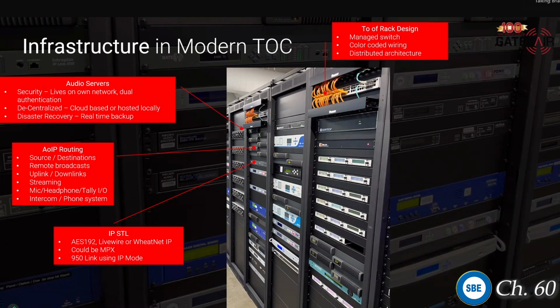And the beauty of that is that with the IP and having multiple paths to the transmitter site, if you lose one path, a piece of ice falls, takes the feed horn off your 950 or your 6 gig dish, it just hitlessly goes to the fiber backup.